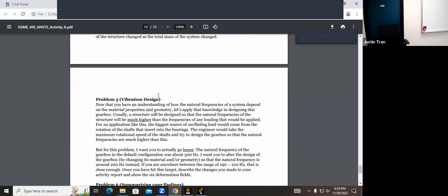A lot of the forces come from the contact of the tire, to the wheel, to the upright, and the contact with the arms. The connection from the wheel is how the forces go through, and the book summarizes this in a few pages and images: the force acting on the inner bearing and outer bearing.